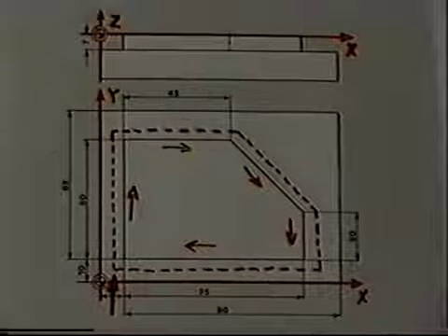Now I program the contour. The control system recognizes that contour compensation is over when command G40 is given. All right, G40. And then I move away again, parallel to the contour, to a distance of 3 millimeters.